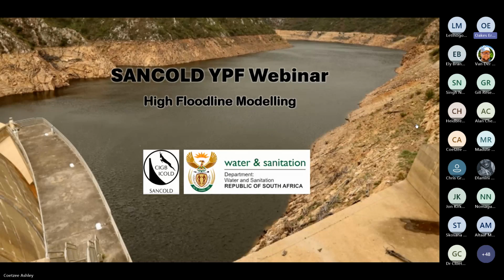Sorry, if I could maybe just come in with a comment. So I think in the HEC-RAS manual, there is a guideline as to the spacing of your cross sections, depending on, I think, the river reach length and that type of thing. But just something to take note of, and this is based on my own experience. It's good to try have as many cross sections as you can, but the problem is that cross sections are not allowed to cross and intersect. So one just has to bear that in mind. It's good to try and load your geometry with cross sections, but they're not allowed to cross at all, which does become a bit complex when you've got a winding river, and trying to go perpendicular to the flow path, etc. So just something to keep in mind. Thank you.